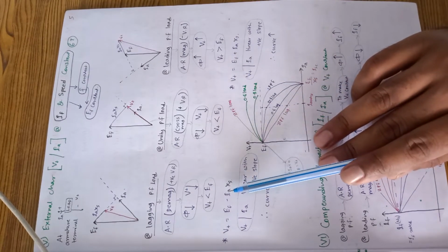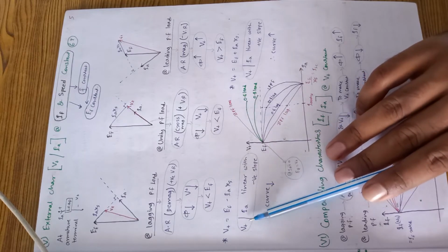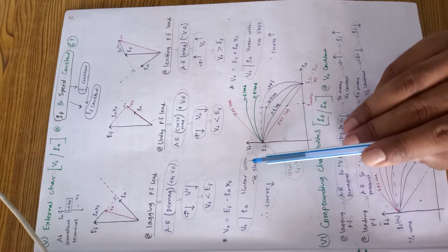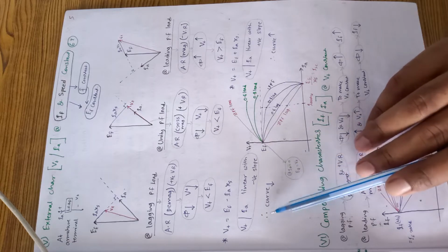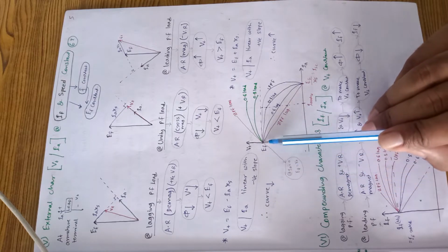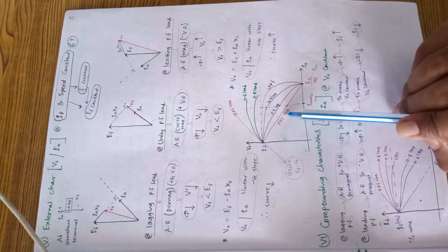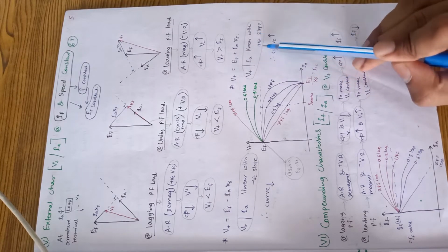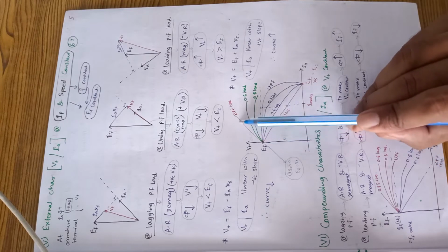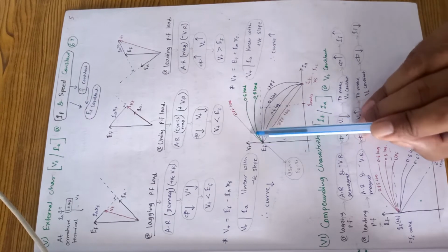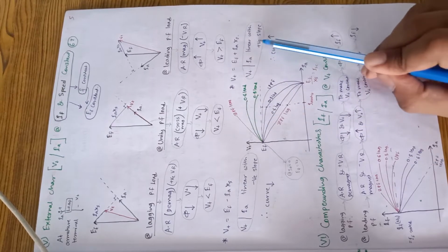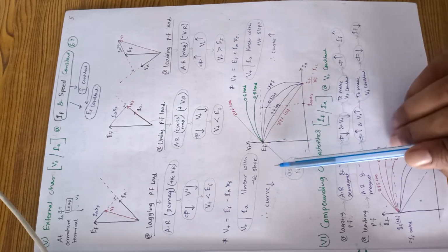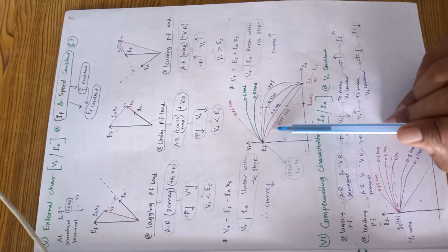So next we have Vt versus Ia. Vt versus Ia is linear with negative slope, therefore the curve decreases. For ZPF lagging, it has a negative slope, and for ZPF leading, Vt versus Ia is linear with positive slope and positive voltage regulation. The curve is increasing for zero power factor leading. For zero power factor lagging, the curve is decreasing with negative slope.